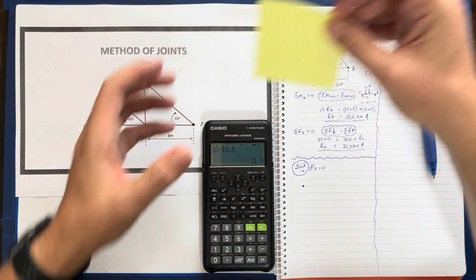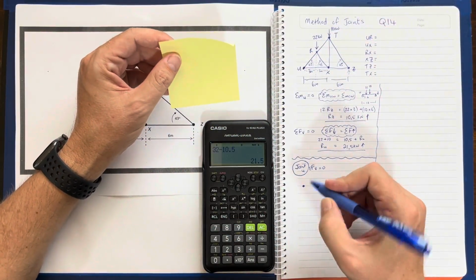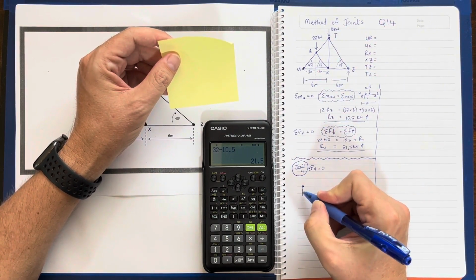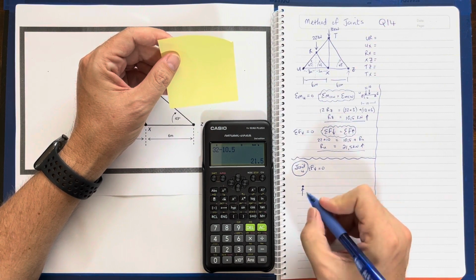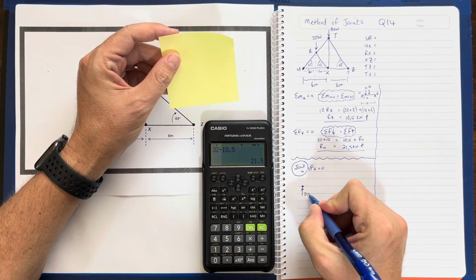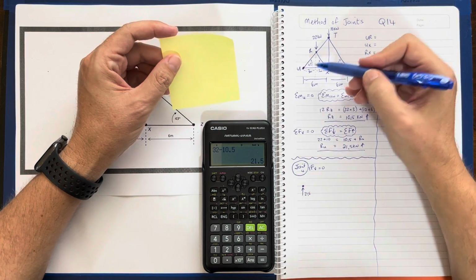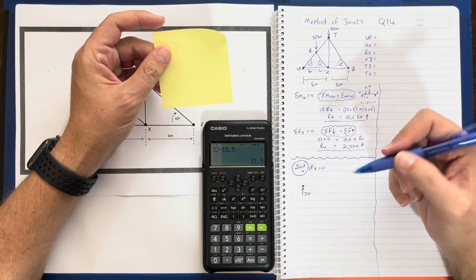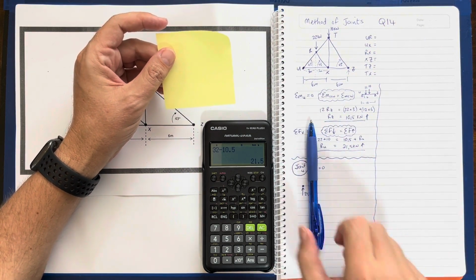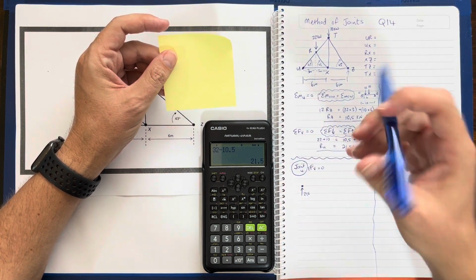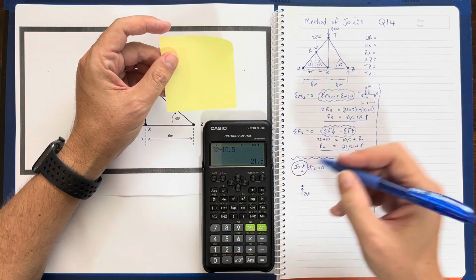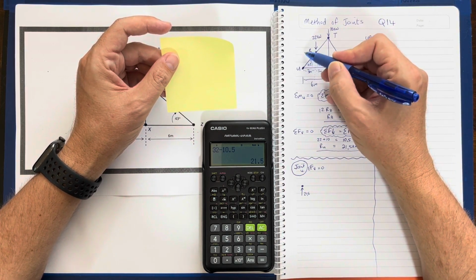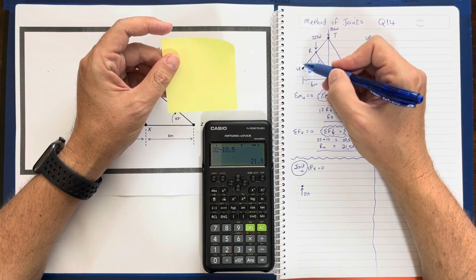You ignore everything else. So what I do is I look and I see what external force is being applied to U. And at the moment I have found that the reaction is an upward reaction, an external force of 21.5 kilonewtons going upwards. And because I'm doing vertical, I can only work with forces that are going to be vertical. So what I do is I look at UR and I say, well, I don't know, that is going to be the hypotenuse of the vertical here. This is the opposite.